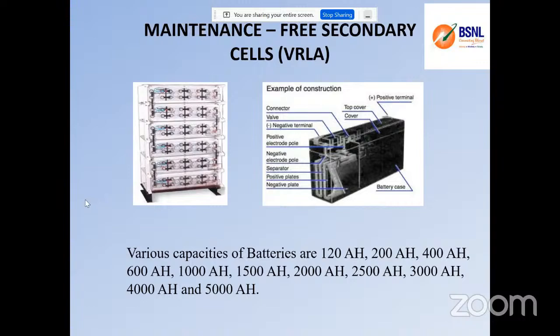So we have various capacities available in VRLA batteries. It starts from even 120 Ah to a maximum of 5000 Ah. Like very big telephone exchanges or very big data centers or very big transmission parts like nodes and other main data centers, we will have higher capacities, so that more loads can be served for longer durations, so we can choose 3000 or 4000 Ah batteries. Maybe at your field visit you can see and realize all this information.